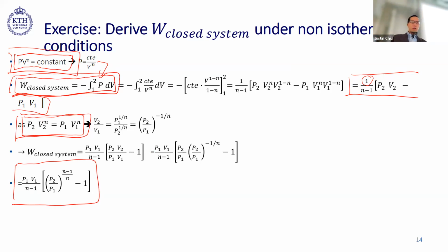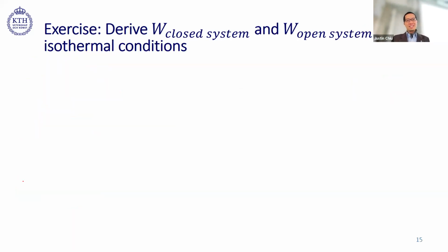So the same, if you know, let's say, initial pressure, initial volume, and the end pressure, so basically by knowing 3 of the unknowns, you can calculate the work that is required. So you can maybe compare the work required for closed system to that of open system for the contour case on your own later on.